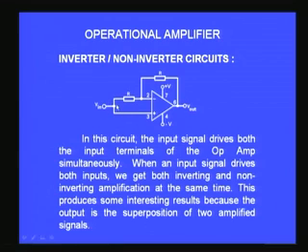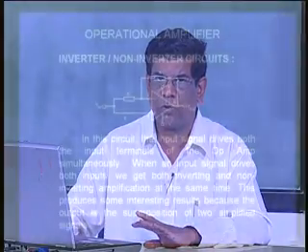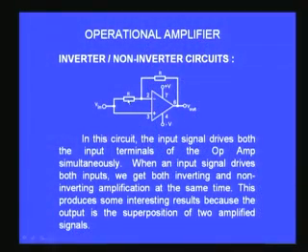and apply the voltage only to the inverting input, then it becomes a very simple exercise because it is an inverting amplifier and the feedback resistor is R, the input resistor is also R, therefore the gain is minus R by R, that means minus 1. So it is a very simple inversion circuit. It inverts whatever is the amplitude at the input correspondingly at the output. It just provides a 180-degree phase shift between the input and output. So when I ground the non-inverting input, the amplifier becomes a very simple inverting amplifier.